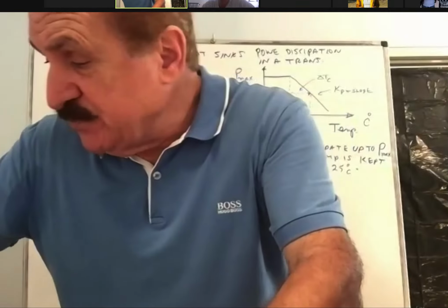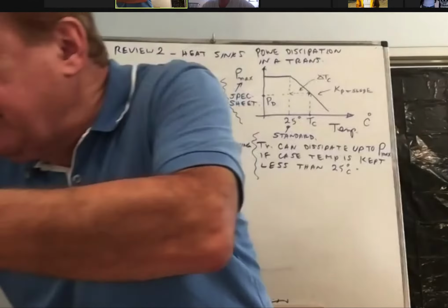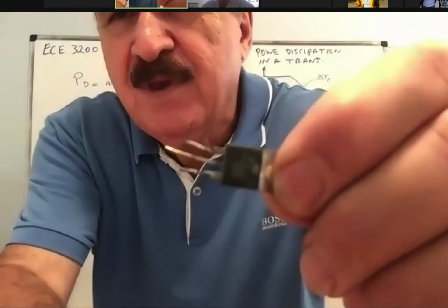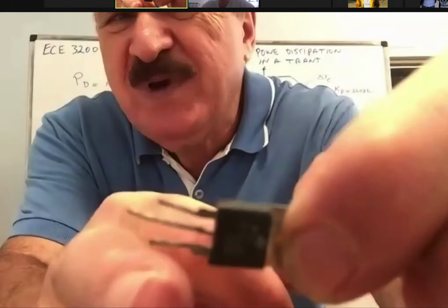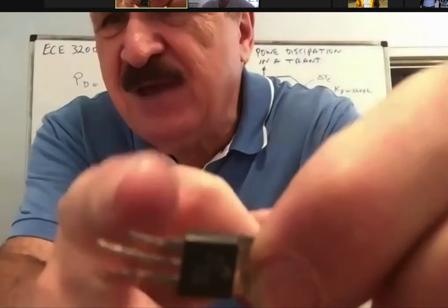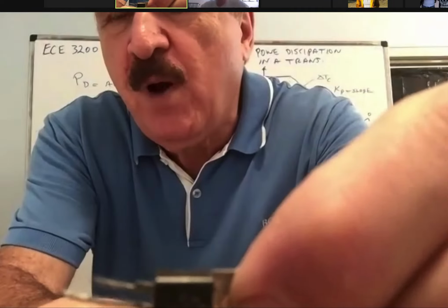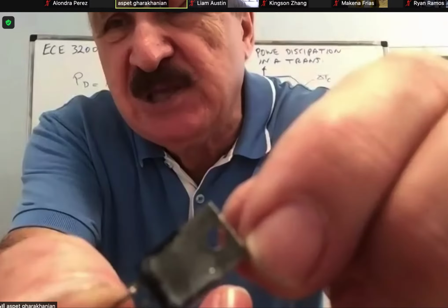There are some others, like this transistor here. This is a medium power transistor. One is base, collector, emitter, one of the three. So you've got to sort it out from the data sheet. But it also has a metal stud, metal casing,